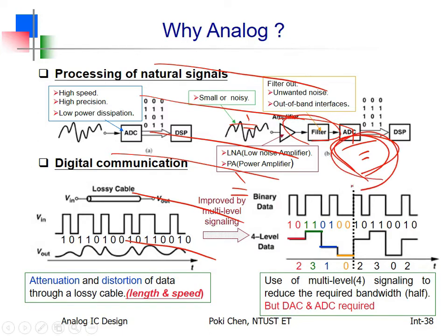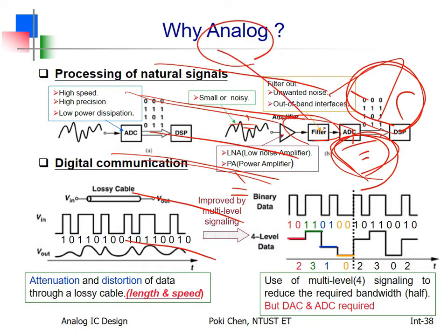Grounded is some kind of AC idea. Only the AC voltage needs to be 0, then it will be good. So it only means that you connect all those shielding lines to a fixed DC voltage. It will be good enough. Please keep this in mind. Especially in analog design, if you see something grounded, don't think it is connected to 0 volt. No, it is a fixed DC voltage. Good enough.